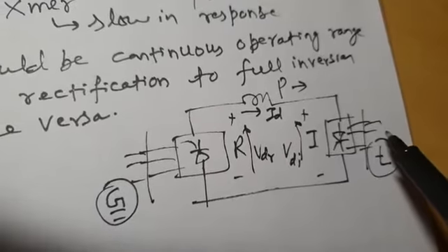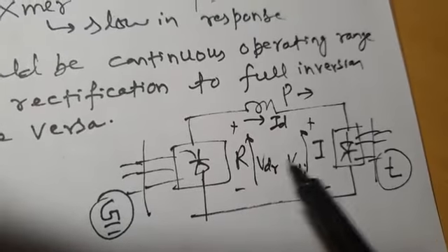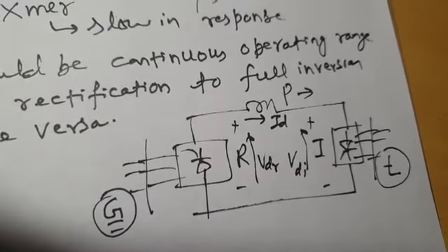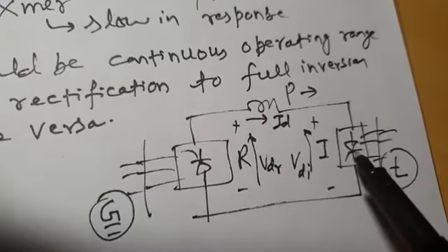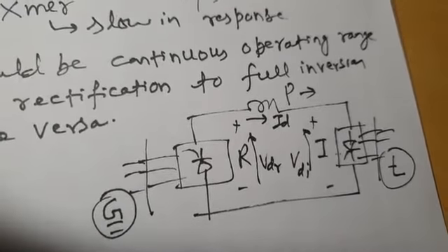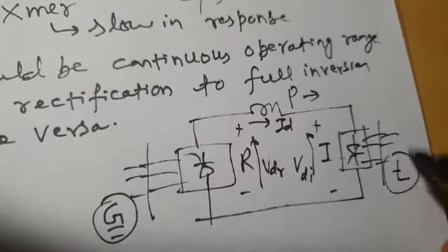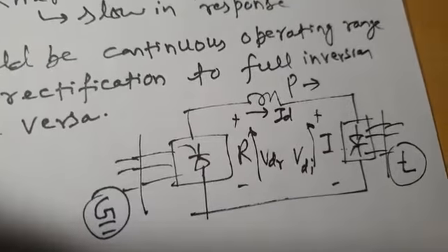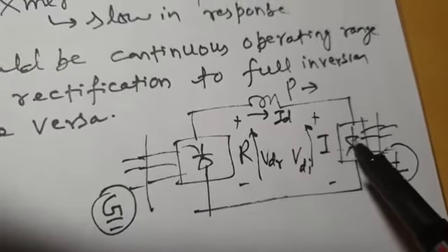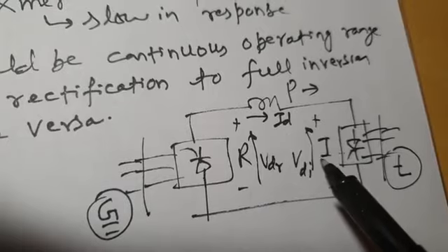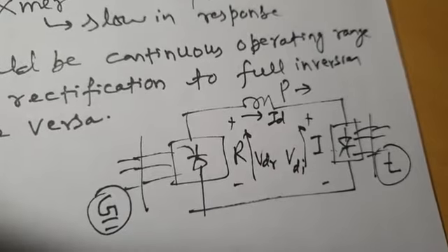And then, the only difference between the normal two-machine model and this two-machine model is that your transmission line in the normal two-machine model is an AC line. But here it is a DC line, because you are converting AC into DC here, and here you are converting DC back into AC. But that is possible only if the AC side already exists on this side, and you have an AC side on this side, okay? When this is also an AC side, this is also an AC side, then only we can say you operate this converter in inversion mode, and in inversion mode, power flows from the inverter to this side. And then on this side you may have load centers and all that.